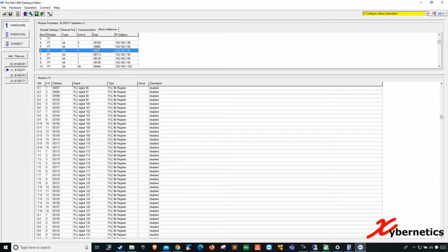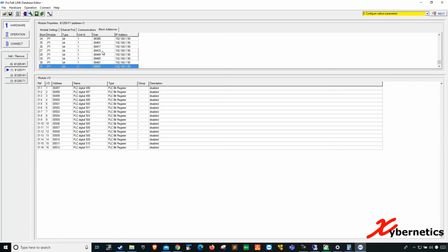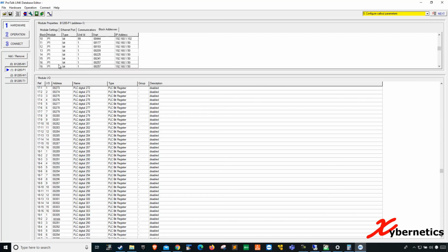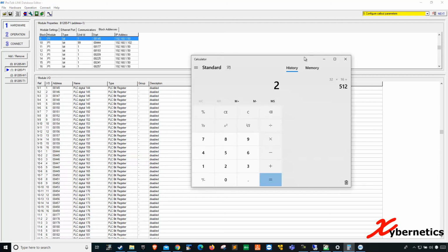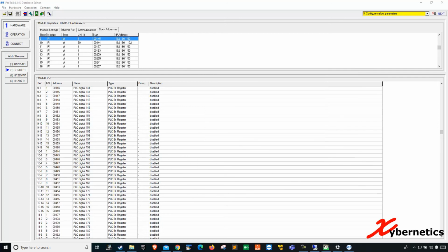So essentially you will have blocks 4 all the way to 32 that you can use. If you do your math, you have block 4 all the way to 32, and each block you have 16 bits to read. There's actually 29 blocks multiplied by 16. You have a total of 464 bits you can read. That's your cap for each PLC module. There's something to note in design.